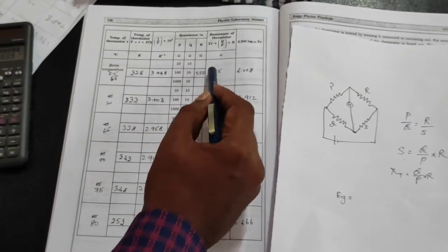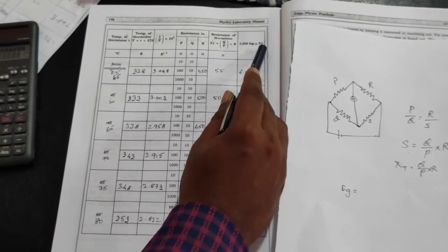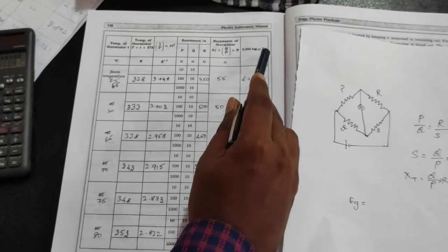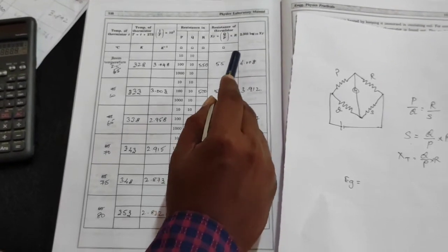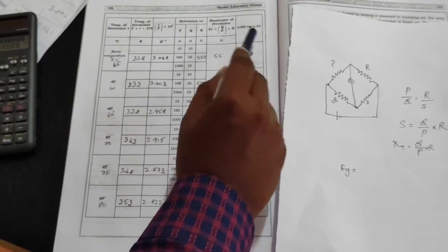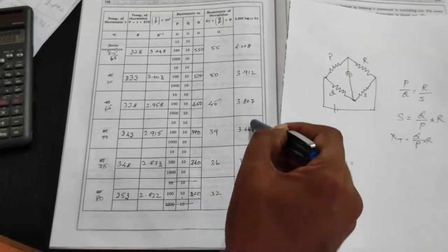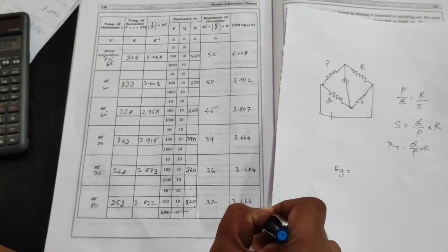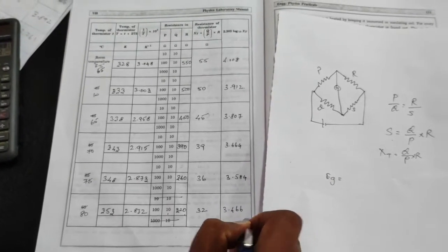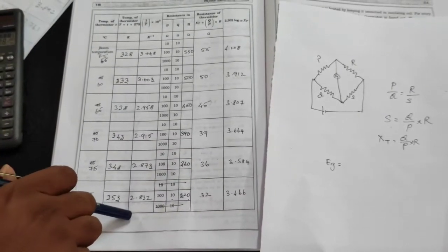And then similarly, using this XT value, I substitute over here 2.303 log base 10 of XT. So just find the log of 55, multiply with 2.303, and you will get the answer. So these are all the values of 2.303 log base 10 of XT for every resistance R with the corresponding temperature, and these are all the corresponding inverse of temperature.